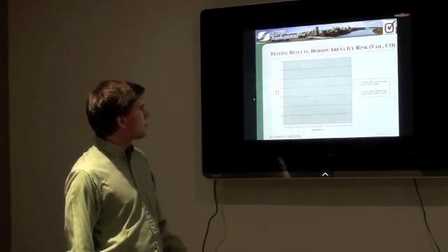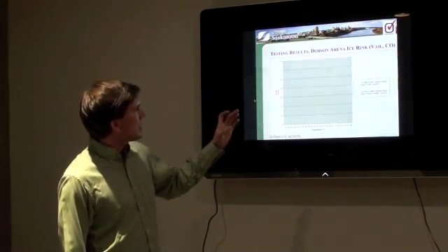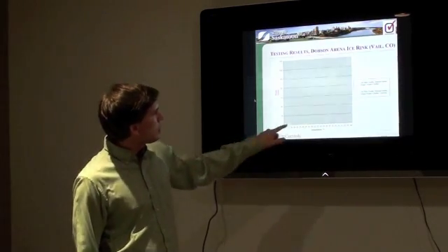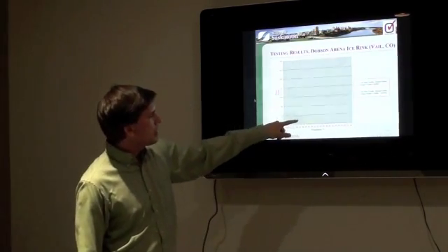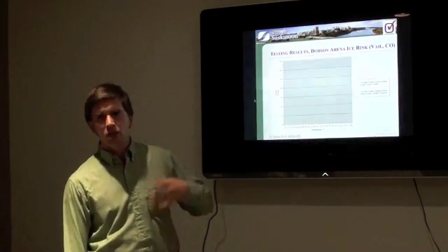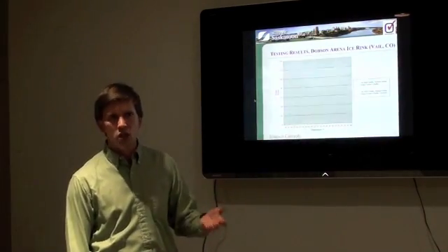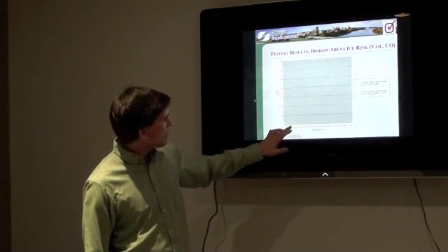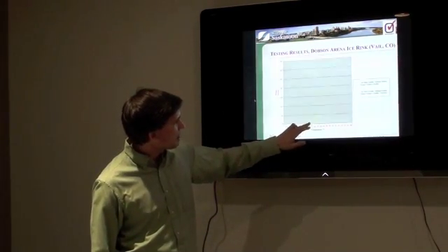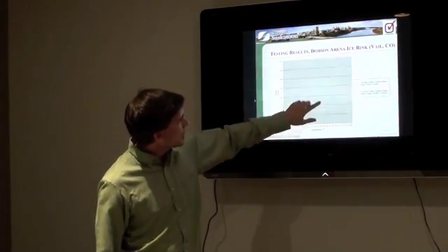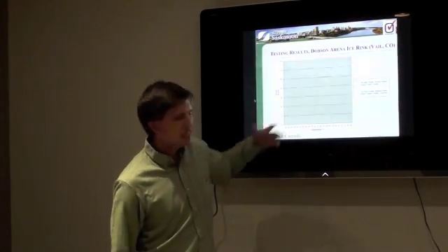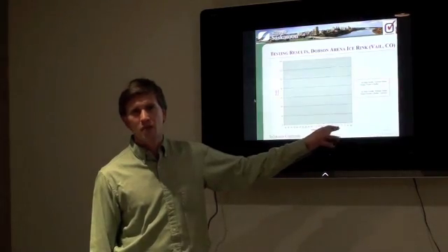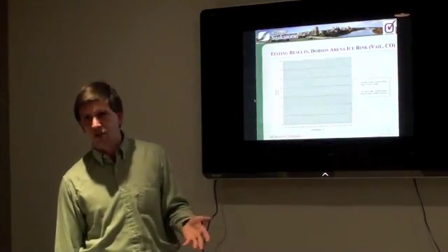So this is like a pilot that was done down in Vail, Colorado. This yellow line is the curve of the temperature they required to get good ice formation under normal circumstances. And you can see the ice actually only starts really forming at about -23 degrees Fahrenheit. You didn't get a really complete freeze in a significant amount of time until about -14 degrees Fahrenheit, which is about -10 degrees Celsius.